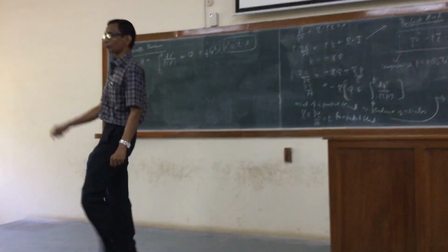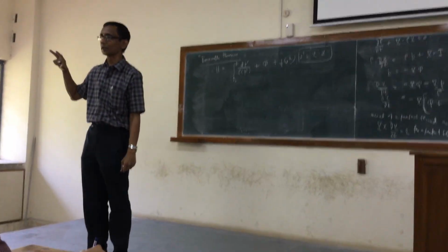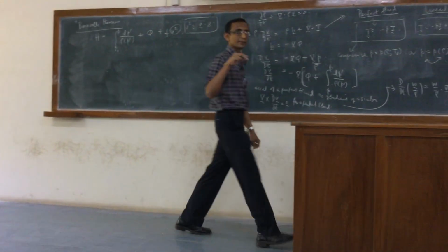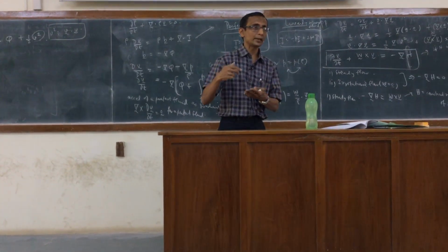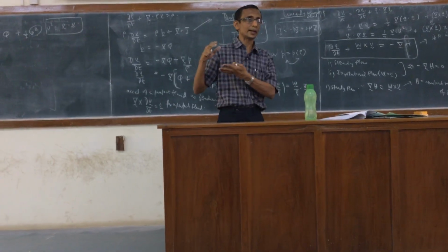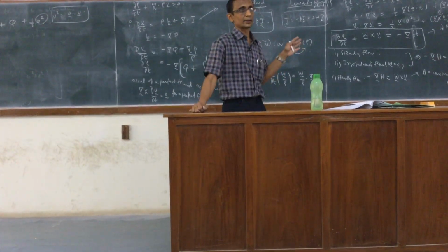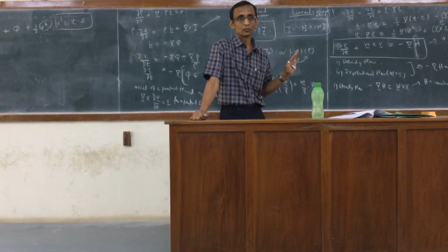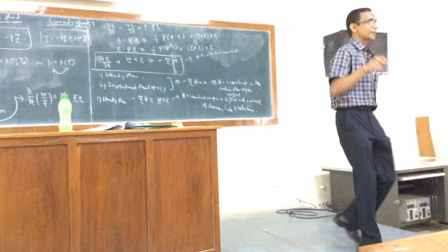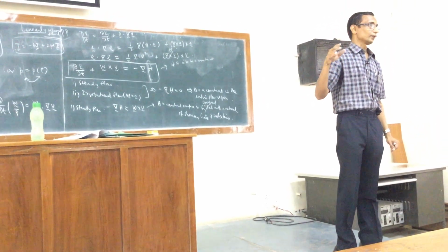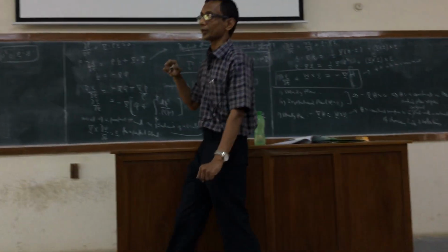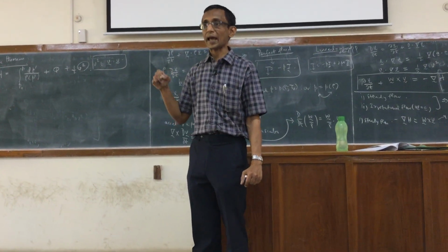So effectively this would mean that h is a constant along a streamline or a vortex line. Now what is a vortex line? You've seen what a streamline is, right? A streamline is one for which the velocity vector is a tangent. If I replace the velocity in that definition by the vorticity vector, then I get a vortex line. So basically, a streamline is one for which the velocity is a tangent at every point on the curve, whereas a vortex line is again a curve in space for which the vorticity vector W is tangent at every point.